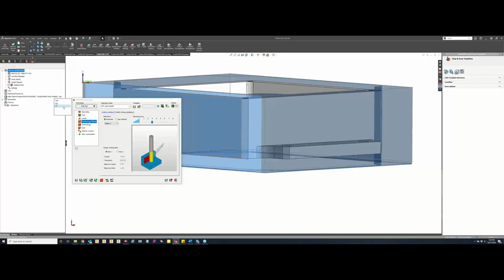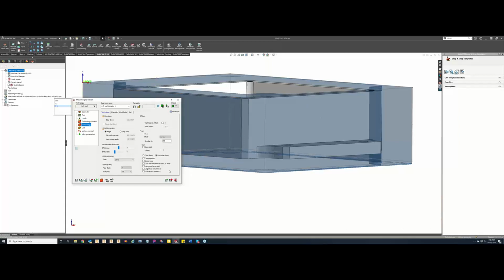Now, my wimpy tool number 4, my 8 millimeter that has a long hangout length, I'm going to dial that one back down a little bit. We're going to run that one at level 4. So now that I have all that set up, I would also like to run compensation for both tools. So I'm running comp right there. I have an Ra finish that I would like to achieve there.